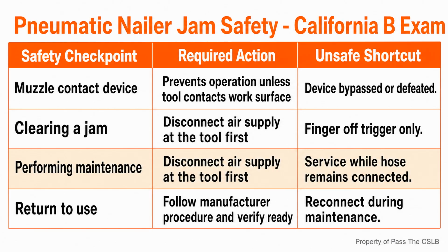This safety rule also helps with quality control. A crew that pauses to correct pressure, depth setting, jams, and tool condition is less likely to keep producing shiners and overdriven nails across an entire wall. Safety and structural quality meet at the same tool.